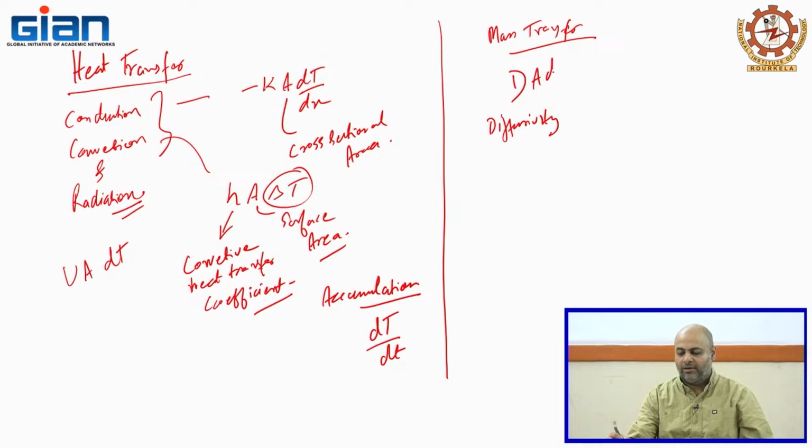So it's D A dC by dx, but it's always like D A dC by dx, where your x is the distance that it has diffused, dC is the change in concentration or the concentration difference, A is your area. But generally when we are working with mass, we always work with flux. When we say flux, it's per unit area, so that's why you will see D dC by dx, because A would have gone on to the other side of the equation to give you the flux.